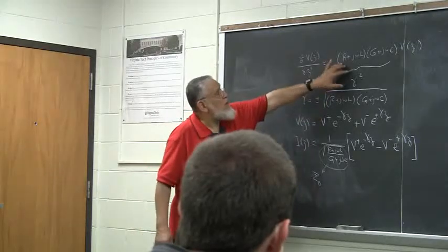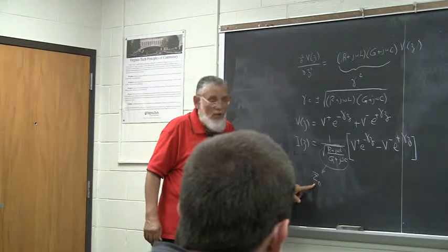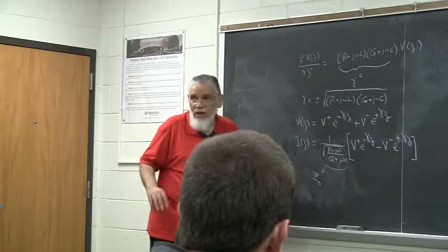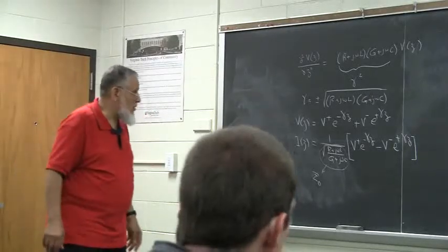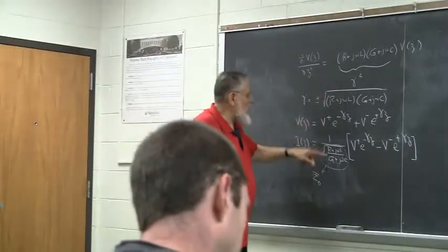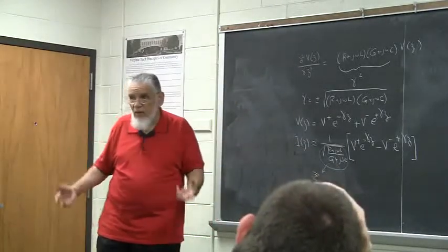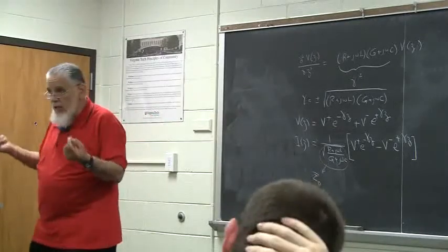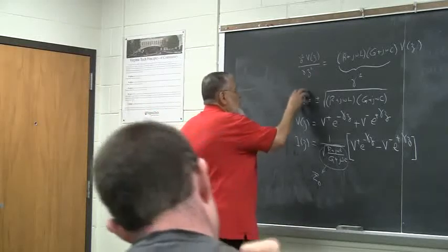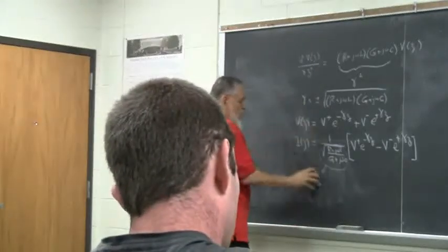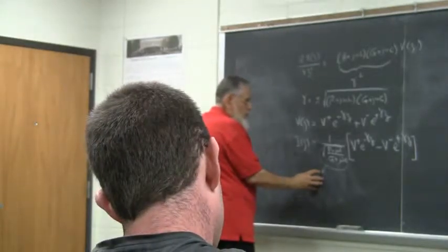We call this quantity here gamma squared. We call this quantity here Z naught. So we're getting rid of RLCG in our discussion now. You won't see them again in the discussion. And we're replacing them with gamma and Z naught. RLCG are real numbers that are physical parameters of the transmission line. And we are translating them to two complex quantities, gamma and Z naught, that will have some physical implications as well. And we'll see in a minute.